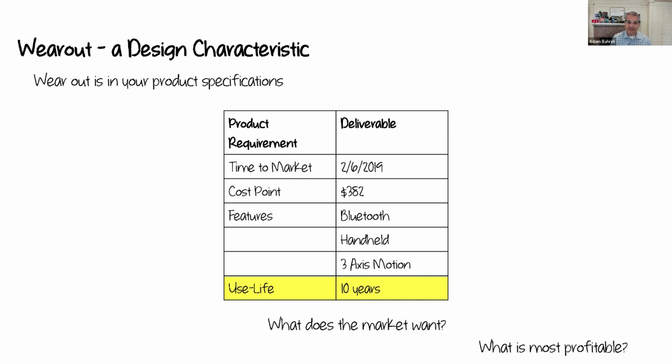And we use accelerated life testing to measure how it's performing, which then may have us do things to change the design to have it satisfy life if it's not. Or maybe we use that measurement to know we can do cost reduction because we have far too long a life, or there might be another parameter that we want to optimize. And in doing so, we would want to be able to measure life because we want to make it shorter.